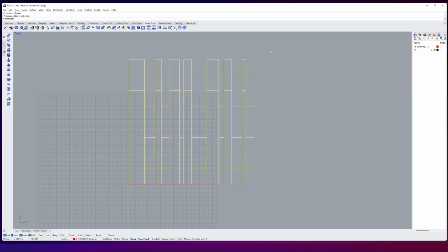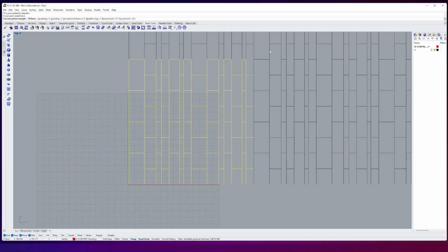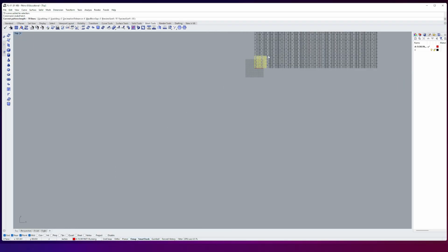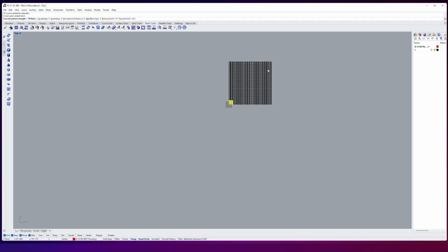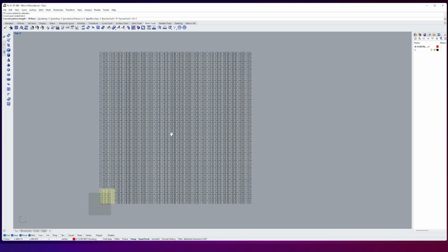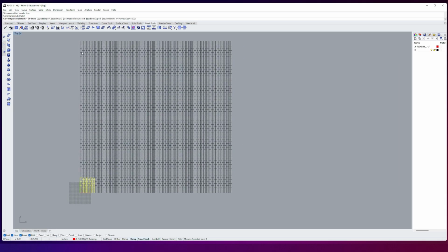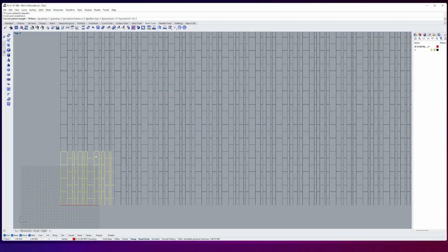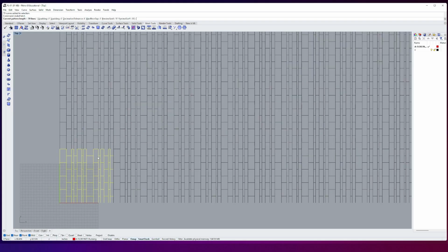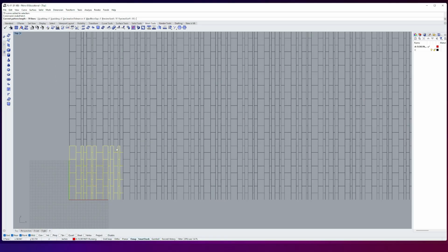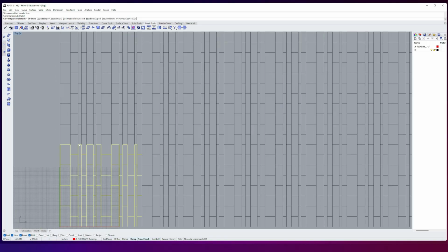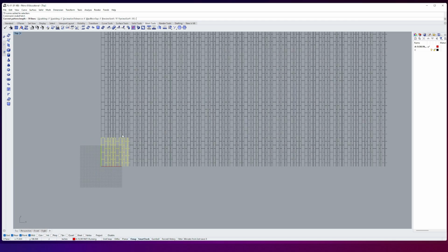Next step would be selecting all of the geometry or the line work, and you're going to type in make hatch. And you can see when you hit enter, it sort of gives you a preview here of a 10 by 10 tile preview of that hatch. And this is kind of how you can tell if it's being built out properly, right? So you can see here, it's repeating nicely in both directions.